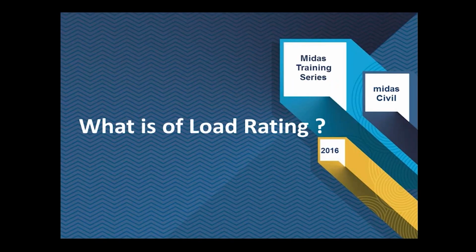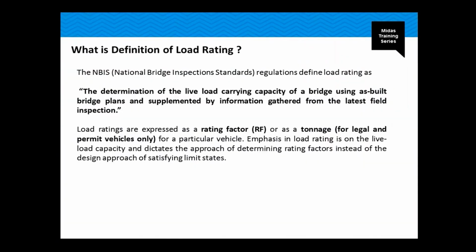Now going into the topic that we're gonna go over today, what is the bridge load rating? The National Bridge Inspection Standards defines the load rating as the determination of the live load carrying capacity of a bridge using as-built bridge plans and supplemented by information gathered from the latest field inspection. It is basically the load carrying capacity of a bridge. It is expressed as a rating factor, which is RF, or as a tonnage, which is for legal and permit vehicles only.